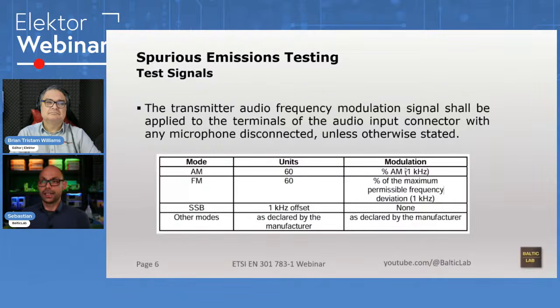The next thing I've never seen, and this is really different from the United States. In the United States, the rules that the ARRL uses in the lab is to use unmodulated signals. In Europe, you should use modulation that simulates voice and the entire spectrum that you would usually carry, but only if it's a non-constant envelope modulation. So AM, for instance, SSB, the envelope of the signal changes by the modulation, and the exact characteristics of these modulation signals is shown here.